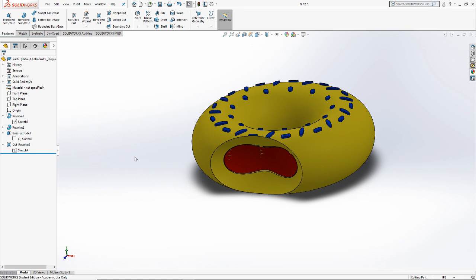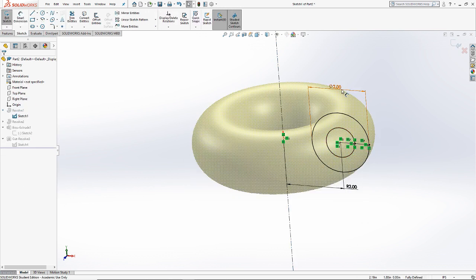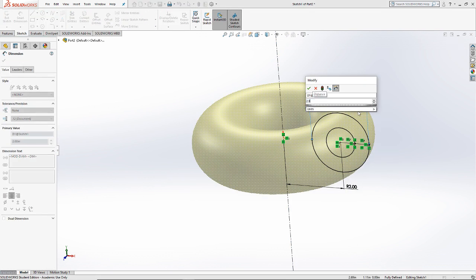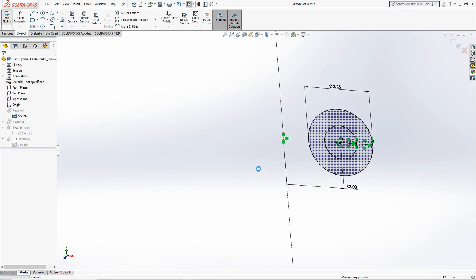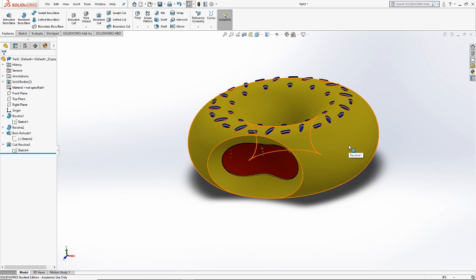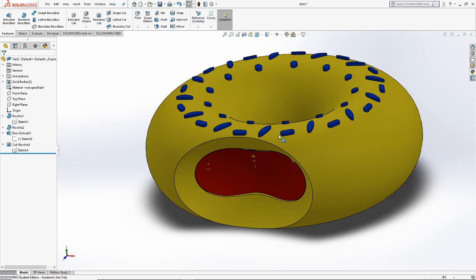I will point out that you want to make sure, generally speaking, that you have it saved as a SolidWorks part file before you export the STL, because the STL file loses all of the intelligence of the SolidWorks part. The convenient thing is that the SolidWorks part is generated every time I open it. If I go in and change something, like I want the outside of the donut to be 2.25 inches across instead of 2, it will rebuild the entire rest of the part around that new dimension. With an STL file, you have very limited control because the STL file doesn't know that it's a cylinder. It doesn't know that it's a torus. It doesn't know that there's a linear extrusion here. All it knows is the edges of polygons. So be aware of that.